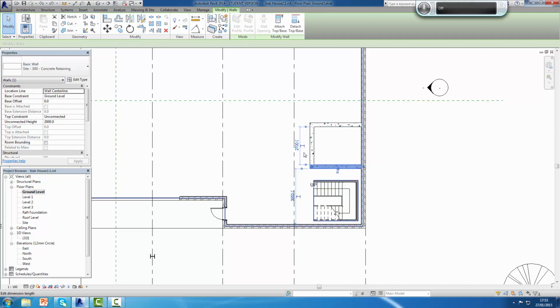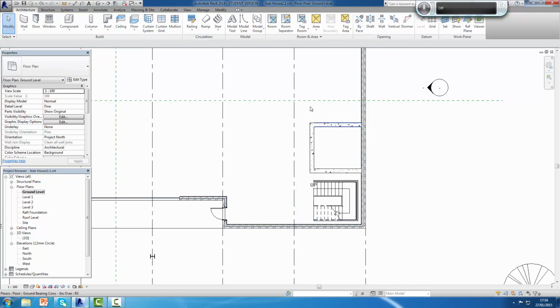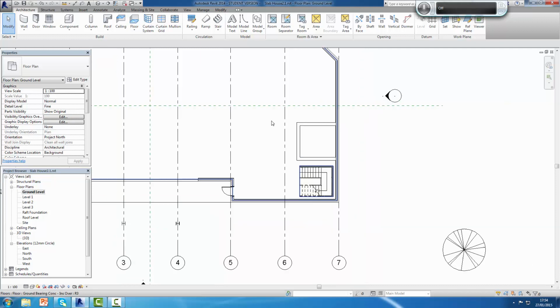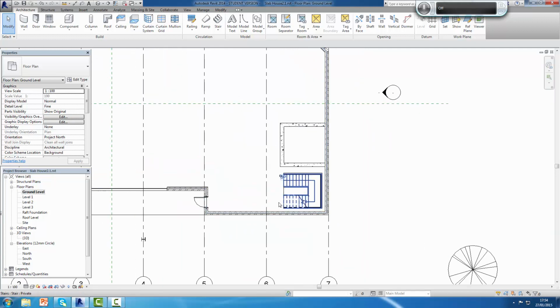That's just showing us that we can edit the wall and make any alterations to what we call a temporary dimension. So I'm going to click on the highlighted blue, and I'm going to change that to 3000. That will now give us an exact interior wall of 3000. Okay, so that's just another way that we can edit any wall when we start putting walls in the actual floor plans themselves. As I say, just temporary ways in which we can control our drawing.